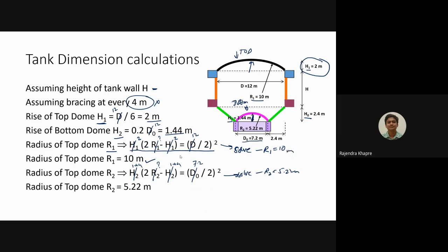In this way, all the dimensions are now known to you. We earlier assumed this value h as 9 meters, but that was calculated using only this portion of the container. So the water here would be 1000, but actually there will also be water in this region. Now we have to calculate the actual capacity, and accordingly reduce the height of this Intz tank.